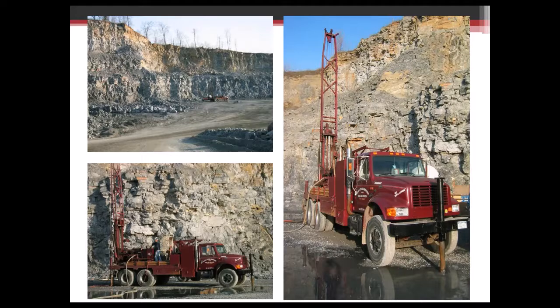One thing that I didn't really talk about much when I talked about the flush joint casing, I mentioned that it was advanced with water. What I didn't mention was how much. Generally, depending on the conditions, you're going to be anywhere from 100 to 300 gallons to advance the casing 5 feet.